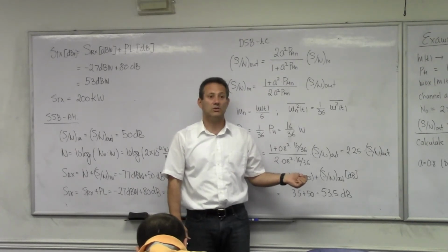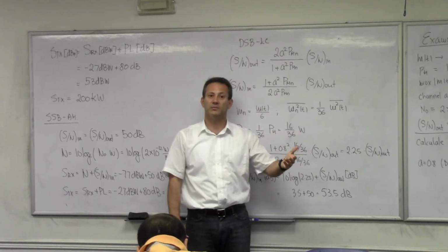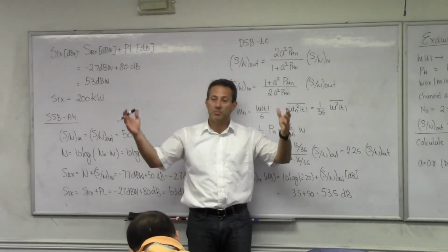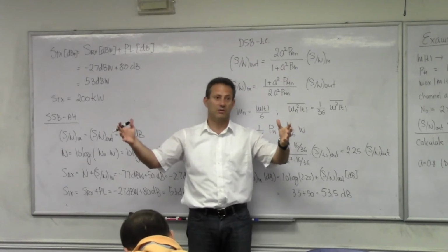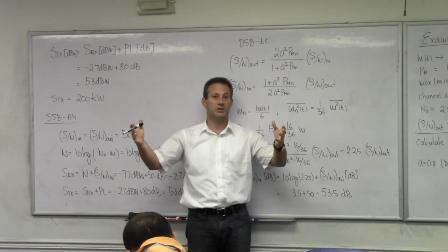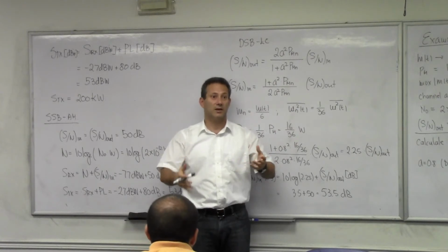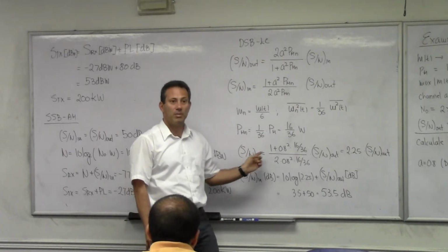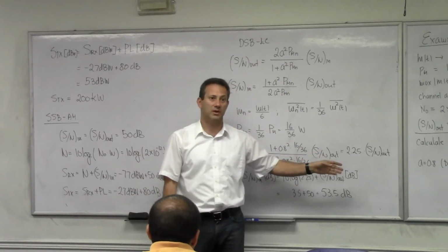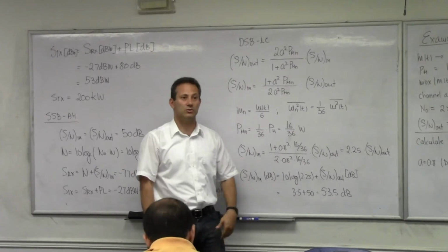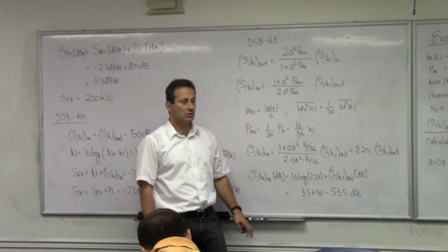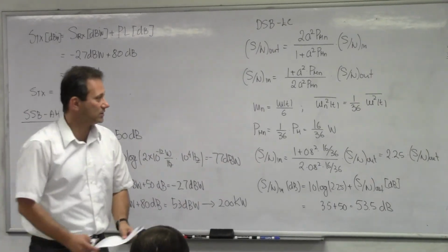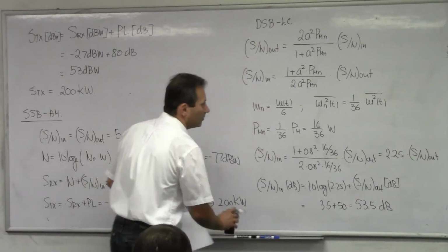It is only used to drive the envelope detector. It is of no use at all. And the big portion of the power that you're sending in your transmission belongs to that carrier. That power is part of the signal at the input, but it's removed from the output. The carrier is just tossed away. You don't present the carrier to the end user. So that's why this one has a negative processing gain, or processing gain smaller than 1.